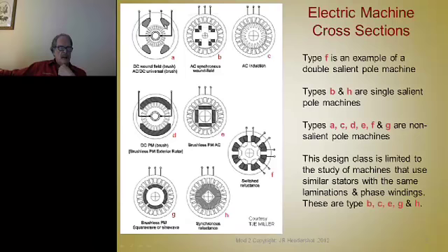If you have permanent magnets here, then you just change the polarity of the armature. Now, what's interesting to note, even by looking at this picture, is down here we have a permanent magnet version of this. Instead of this wound electromagnet, North Pole and South Pole here, we have a permanent magnet. Now, there are no wires connected to that, so the flux from this permanent magnet is fixed.